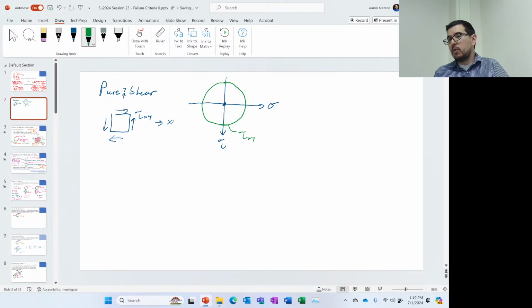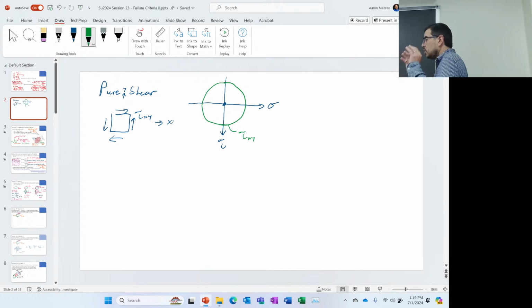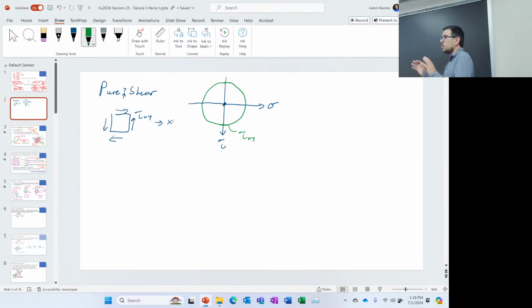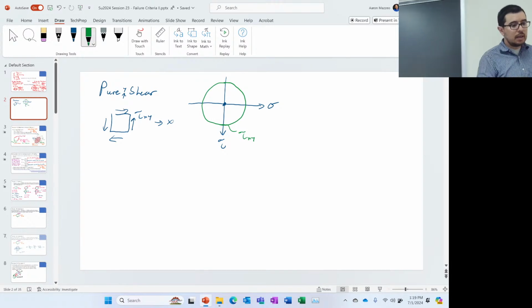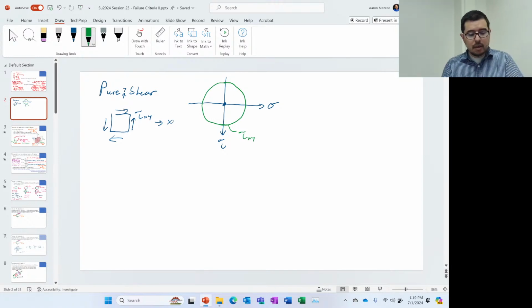Okay, that's for the given load. We're going to talk about this a little bit, but sometimes you're drawing more circles to describe the load, and sometimes you're drawing more circles to describe the testing that was done on the material. But if it's a test, it's usually only uniaxial loading, because that's pretty much all we know how to do in this class, which is fine. This is a great test. So that's the operating load, this is the operating stress.